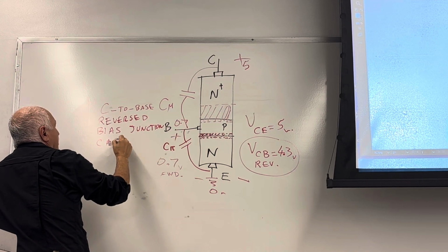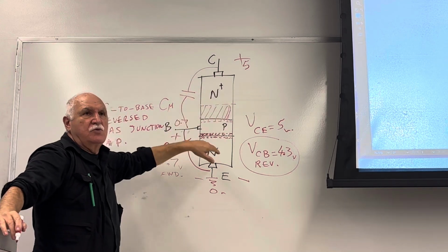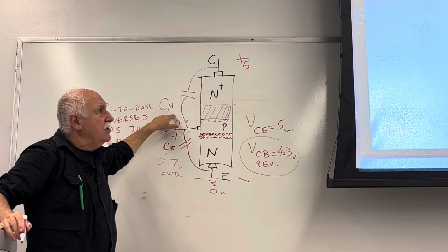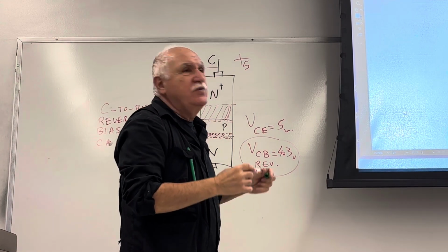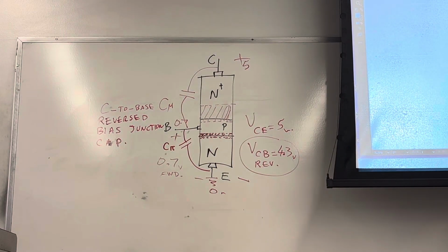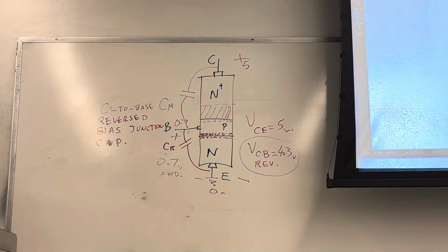capacitance. It has nothing to do with the current that goes through, but it has to do with the amount of the voltage that reverse biases. Okay, so what do we get now? Go back to the transistor model. I'll show you in here. Okay, let's review our transistor model, R-Pi and the GM. Do you recall that, R-Pi GM? We didn't have this before. These two caps were absent.